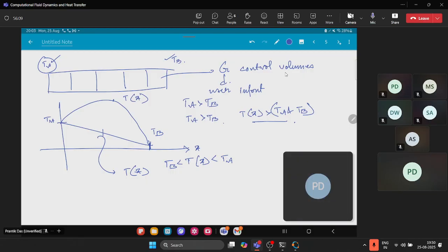That should be the case because if there is a source term, it will receive more heat, so the temperature will be higher than the temperature present at the boundaries. रॉड का अंदर जो है अंदर टेम्परेचर ज़्यादा होगा compared to that of the temperature present at the boundaries because we are using some volumetric source over the whole domain itself. But if it's a diffusion problem without any source term, the profile itself will be a linear one. Okay. So is it clear to all of you?